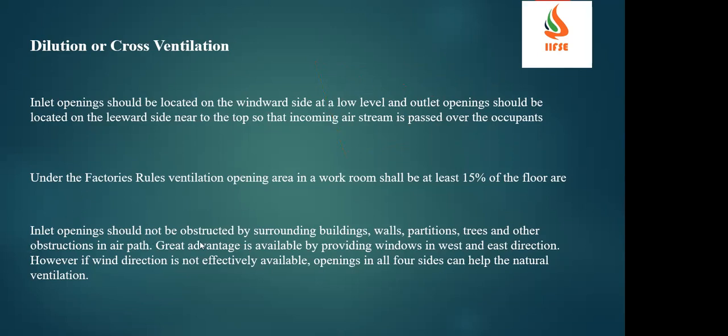Now, the inlet opening should not be obstructed by the surrounding buildings. This is also one of the key aspects we have to consider whenever you are giving any specific openings. It should not be obstructed by surrounding buildings, walls or any other portions, or any trees or other obstructions in the air path. These are all things we have to consider wherever you are giving an inlet opening for your building.